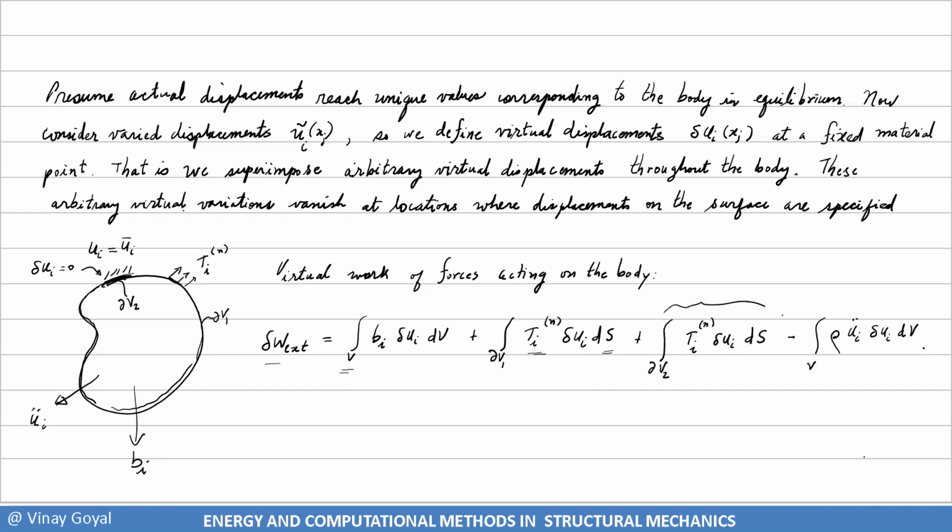So you can see here that I can apply Cauchy's relationship. I'm going to just combine these two integrals, but I want you to realize I can apply Cauchy's relationship here to relate the tractions to a cube inside the body, because that's where failure could occur. So I want to draw a free body diagram there to proceed forward. So that's sigma_ij n_j del U_i, and here as well. I'm going to combine these integrals because I can. You can combine two integrals, and we know this one is zero, but it doesn't matter. I can still combine them.